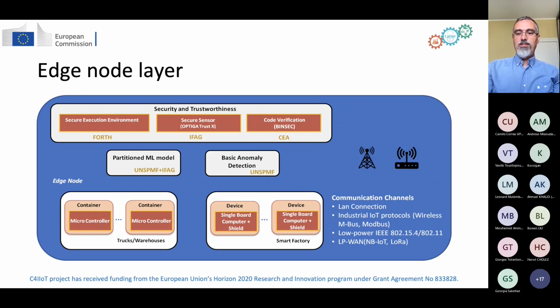There's actually a neural network autoencoder with one hidden layer running on each of those microcontrollers. They have been pre-trained with real world data, so in this sense, we have anomaly detection even within those devices that we've designed, within their firmware.